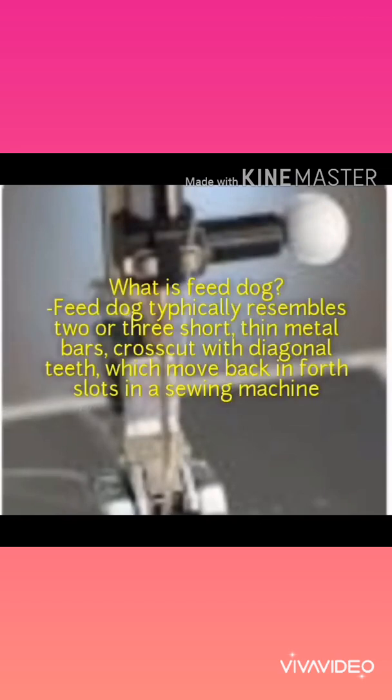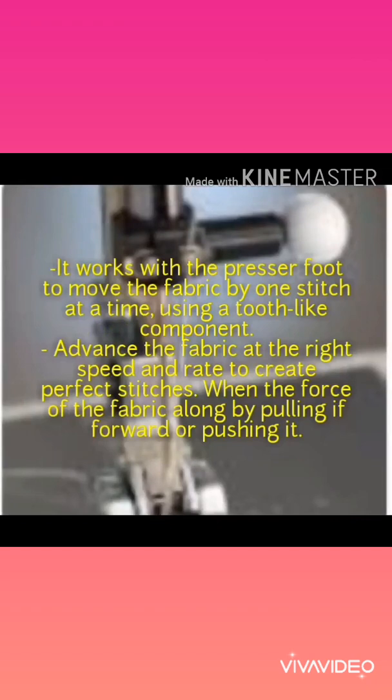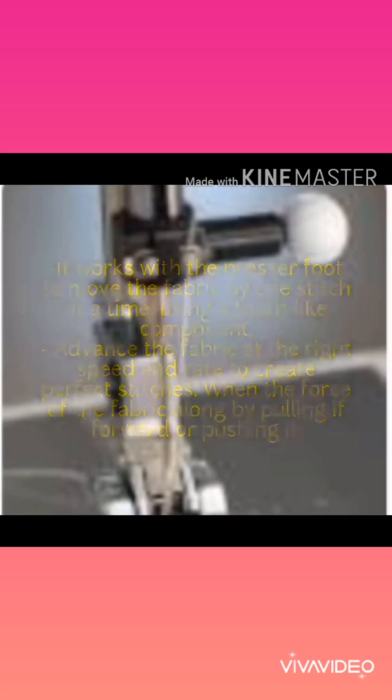Feed dog. What is feed dog? Feed dog typically resembles 2 or 3 short, thin metal bars, crosscut with diagonal teeth, which move back and forth in a slot in the sewing machine. It works with a presser foot to move the fabric by one stitch at a time, using a tooth-like component. It advances the fabric at the right speed and rate to create perfect stitches, by pulling it forward or pushing it.